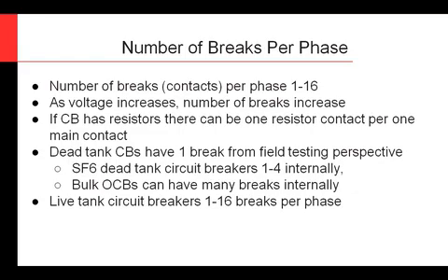Now, a dead tank circuit breaker, from the field testing perspective, you only have one break per phase. You'll just see the bushings and hook to both sides. But internally, these can actually have anywhere from 1 to about 4 breaks. Same thing with bulk oil circuit breakers. From a field testing perspective, they're 1 break per phase, but they can have multiple breaks inside.